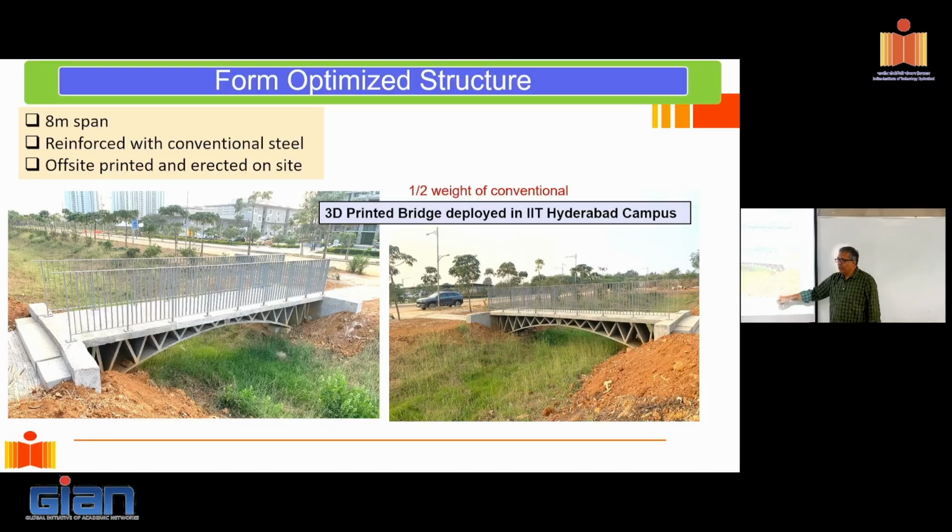Now what we're doing is trying to look at the carbon tag, because these mixes are cement rich. I will not deny that. The reason is aggregates are smaller. Currently we are printing with 4 mm aggregate, which makes the concrete a cement rich mix. So compared to conventional, we take double the amount of cement. So whatever savings I have here, if you look at it in terms of cement, although I'm saving the weight by half, because I'm consuming double the cement, it basically breaks even.